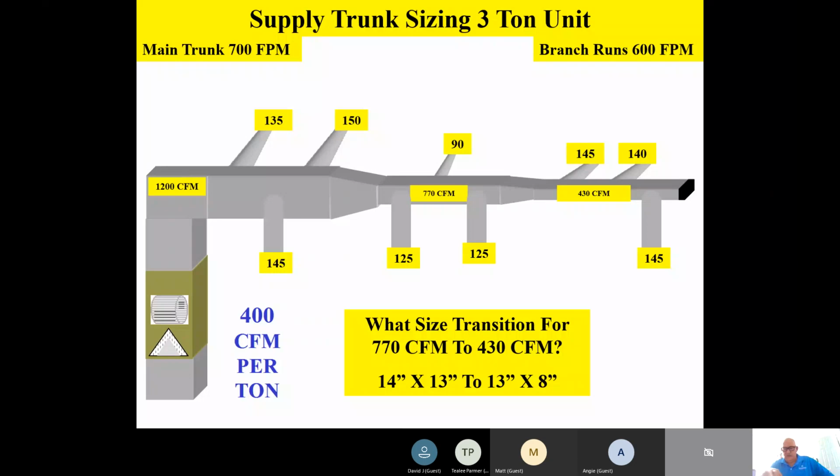So if you're not going to do the heat load calculation, the cubic feet method is a pretty good one. I used that for a lot of years. You take the length times width times the ceiling height, multiply by 5 or 6 air changes per hour, and divide by 60. That gives you the actual CFM for that space. Has everybody got that? Is that pretty well explained? Questions or comments?